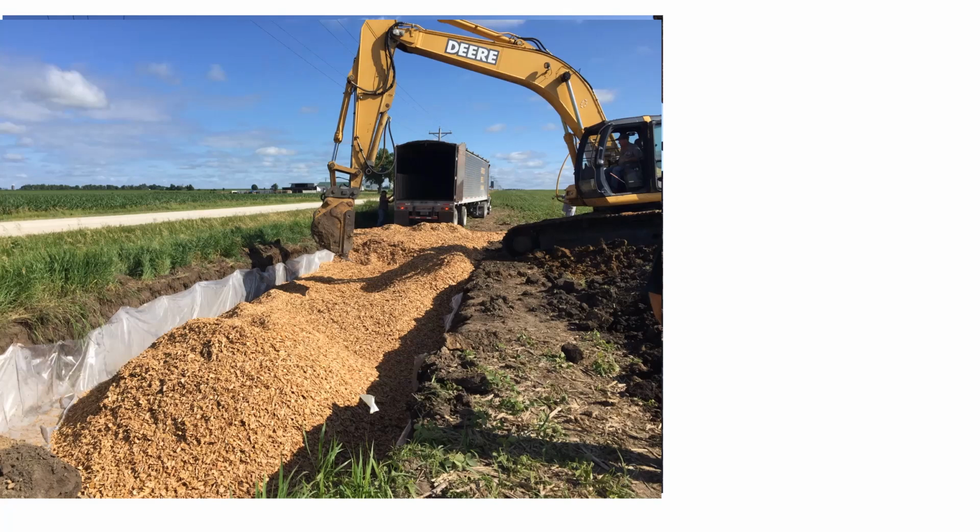The design will have a depth of wood chips that's needed. Really, the most important thing is to make sure we're not going to get too much overburden on that with the soil cap that you put back on top. So once again, if you're at those deeper bioreactor sites where that main's 6 to 8 feet down, you're probably going to have 5+ feet of wood chips in there, just so you're not putting 4 feet of topsoil over the top of that. If it's a 4-foot tile, you're generally looking at about 3 feet of wood chips. You want about 18 to 24 inches of overburden on it.